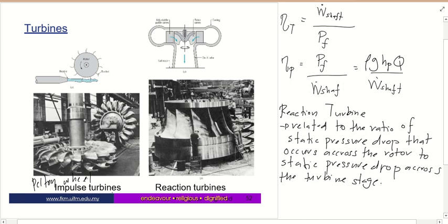In this turbine, the total head, which is the sum of the pressure head, velocity head and elevation head from the Bernoulli equation, is converted into a large velocity head at the exit of the supply nozzle. Normally the impulse turbine comes with a lot of nozzles.